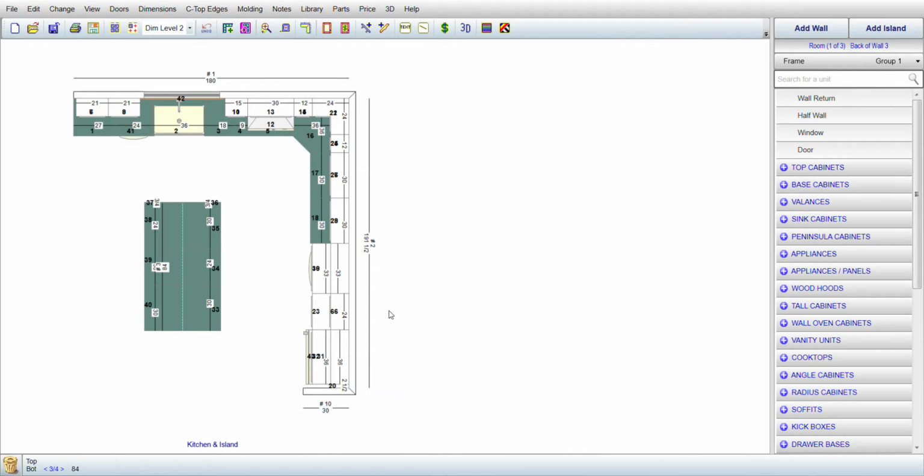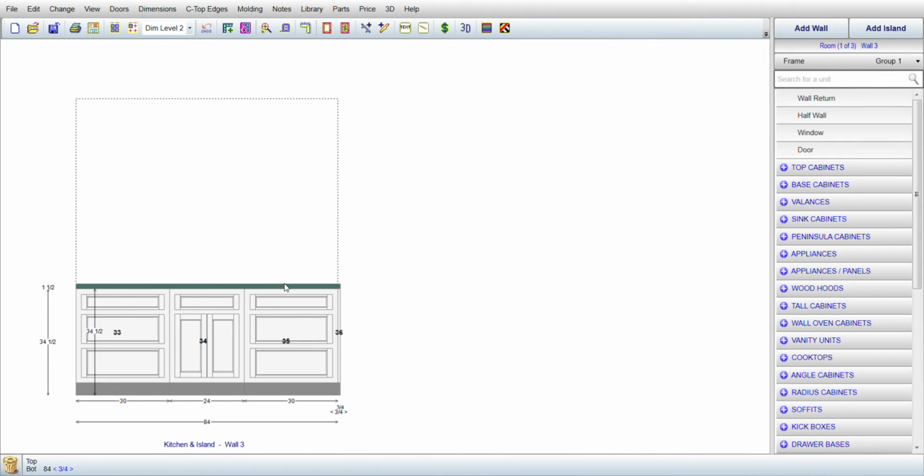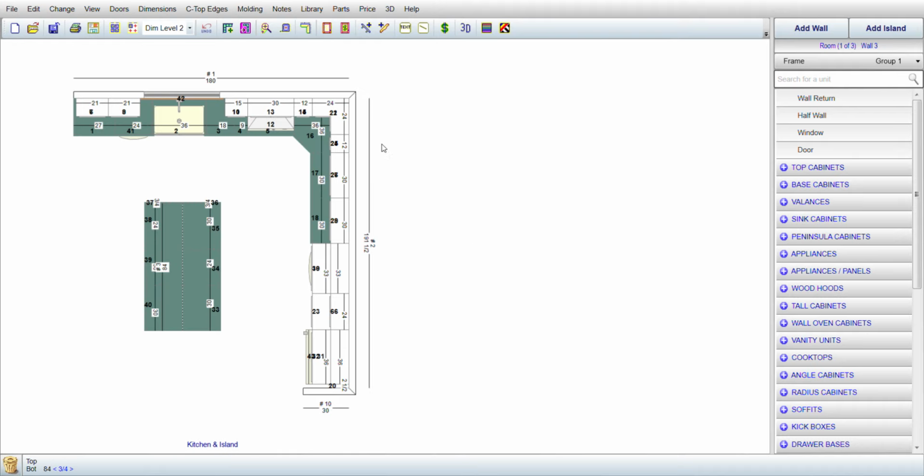With this software program, we're able to determine exactly what parts are needed, as far as how many toe kicks, how much crown, whether there's skin. Sometimes, depending on the manufacturer, you need a skin panel for a finished end. It also helps to know whether there's a wall here. See, there's no wall here, so you're going to need a finished end, whereas here you've got a wall coming out, so here you typically put a filler.